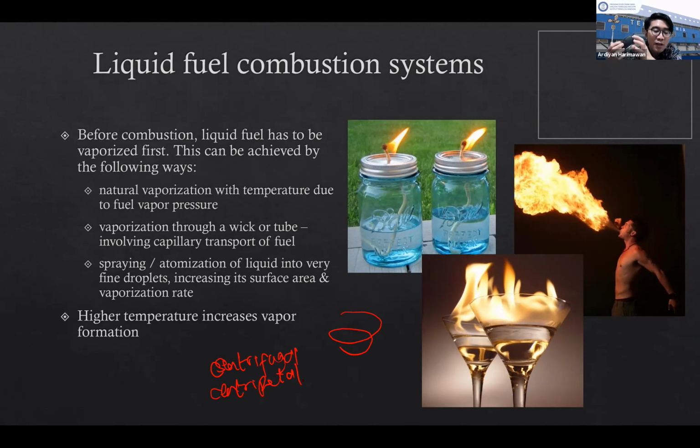So the air will be moving in the rotation movement, so it will experience the centripetal and centrifugal force as well. What will happen? The air will contain the ash, right? The fly ash, and then the entrained gypsum and other particulates. So these particulates will settle down because of these two forces. Yeah, that's the basic principle of the cyclone.